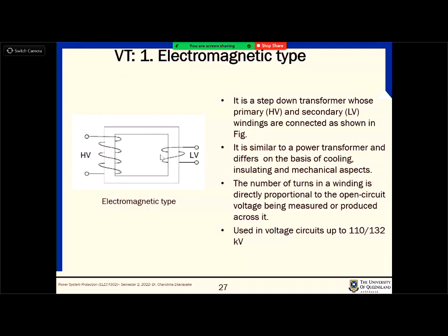And also, in reality, you need to cool down the losses created by the magnetic material or the losses in the winding. So sometimes these VTs are enclosed in an oil bath. That is a very common practice. That's why you have seen that big column in the transformer, inside which you will have a lot of oil, right? And then one end of that coil, the big bushing, is a sort of oil bath where you have these windings immersed.